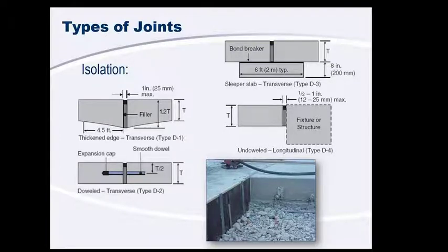This practice actually degraded the performance of jointed plain concrete pavement because when you add that additional space in there, what ends up happening is your slabs start to migrate apart from each other and basically have bigger gaps at your construction and contraction joints than you would want. So basically that extra gap that you leave in there as the expansion joint eventually gets filled up by all of your other joints. So it didn't work quite as well, and for that reason expansion joints aren't really recommended.